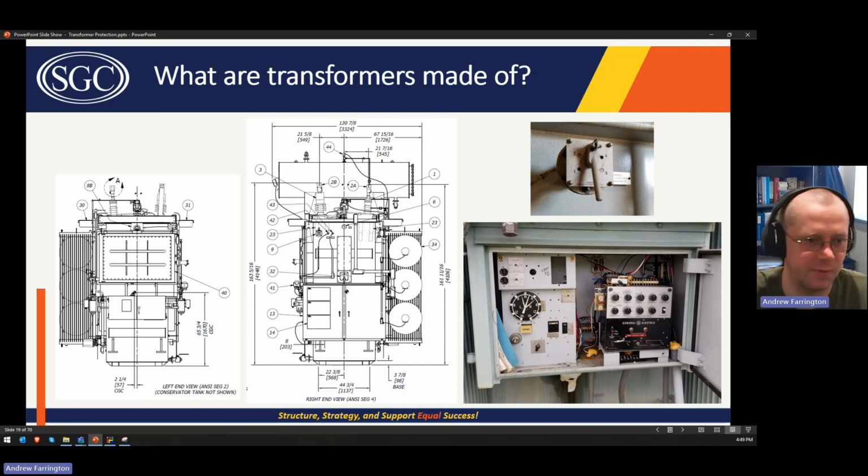So you can have a VT that's feeding this thing 120 volts, and it sets the band center at 120 volts, and then there's a bandwidth of, say, 4 volts. So you can go down to 118 or up to 122, but if it gets outside of that area, this LTC controller will detect that and then automatically change the LTC position to keep it within that band. So that's I guess the theory behind that at a super high level.